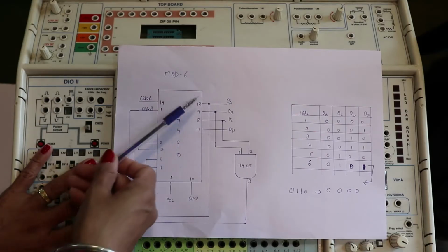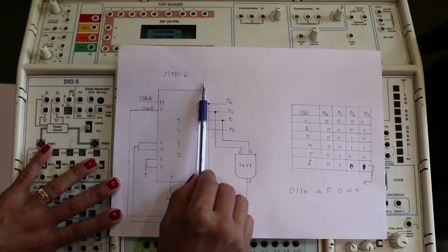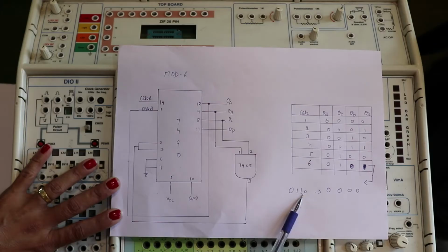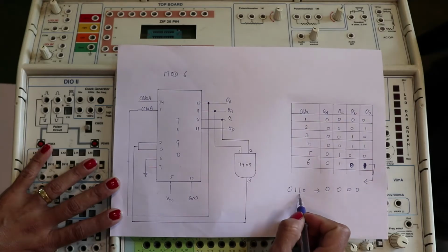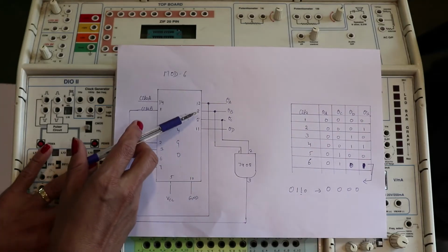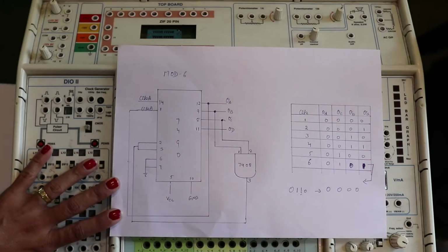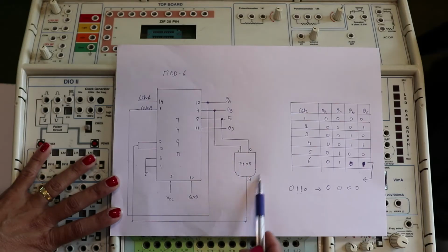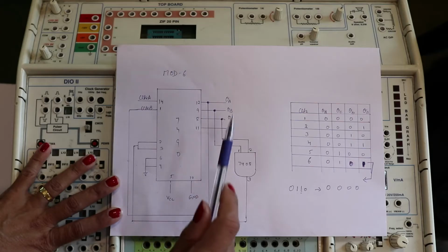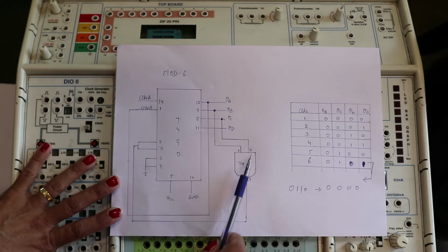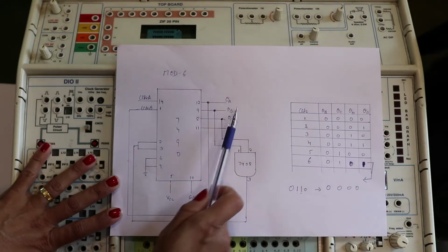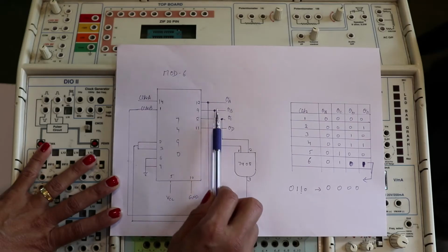After this we want to make it MOD-6 from the total count 0 to 9. For that we want to reset these pins to make the value 0. Which values are those? QB and QC. According to the circuit design, if we use an AND gate we can make the output value 0, so we are going to use an AND gate to reset the counter, or we can say preset these outputs from 1 to 0.